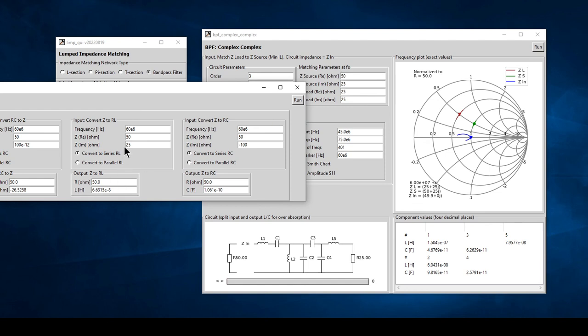Let's look at the load. It's 25-25. We can run that, and we get an inductor for our load of 66. In this case we have an inductor of 79. So once again we must break this up into the value of our load inductor, and the rest then becomes part of our matching network.